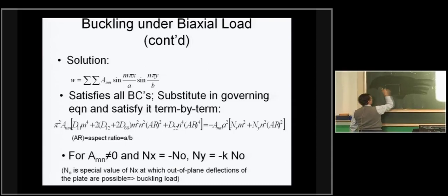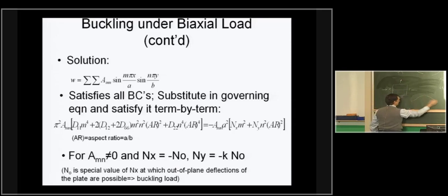If I have a plate and I look at it by making a cut here, let's say under this kind of loading, if it looks like this, this is the shape at this location here. I have one half wave, M equals 1, let's say in the x direction. Now if I were to make a cut and look at it this way, if I saw something that involves two half waves, then I would have N equals 2. And essentially my shape, if I could draw it, would look like this.